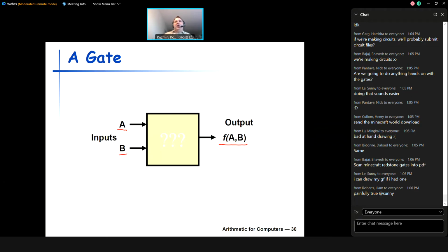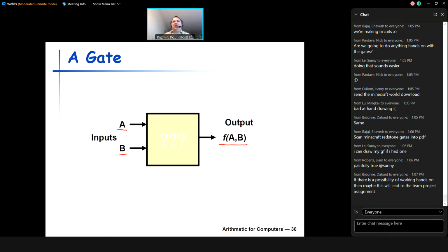Okay, so you don't have to recompute or refresh. The output reflects the state of the inputs. It's the easiest form of circuit, and it's called a combinational circuit because it has no memory, right? The output is in a straightforward manner a function of the inputs.